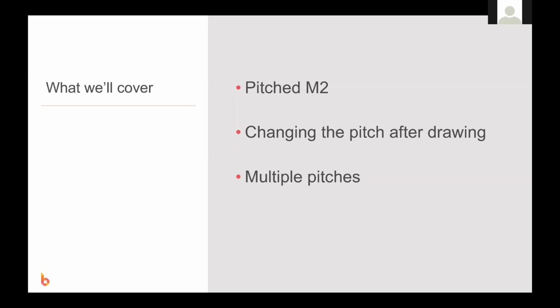So in this video, we are going to look at pitched square meters and how to use Buildxact to effectively complete square meter measurements for angled or pitched surfaces. We will also look at how to change the pitch after completing a drawing, as well as how to deal with multiple pitched surfaces on the same plan.